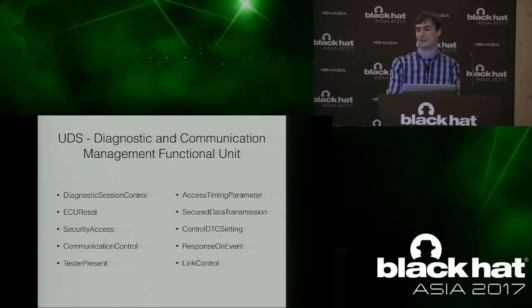Tester present just tells the ECU you have a tester there and stops it from timing out. Access timing parameter is used for some timing settings that honestly I've never really needed to deal with.